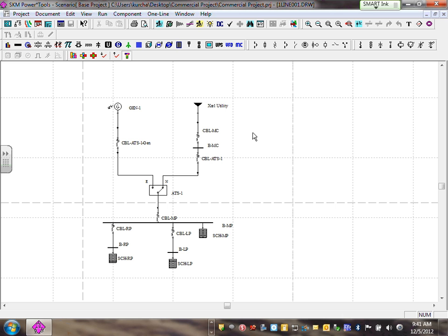So everybody inputted the utility, generator, transformers, ATS, as well as the schedule, right? For the most part. Okay. Next, like I said, we need to go to the one-line diagram. The first thing, Kerry, my friend, here's a one-line diagram. That's what you're going to print for Chad. It's done. The second thing is the short circuit report. Let's go run the short circuit report.